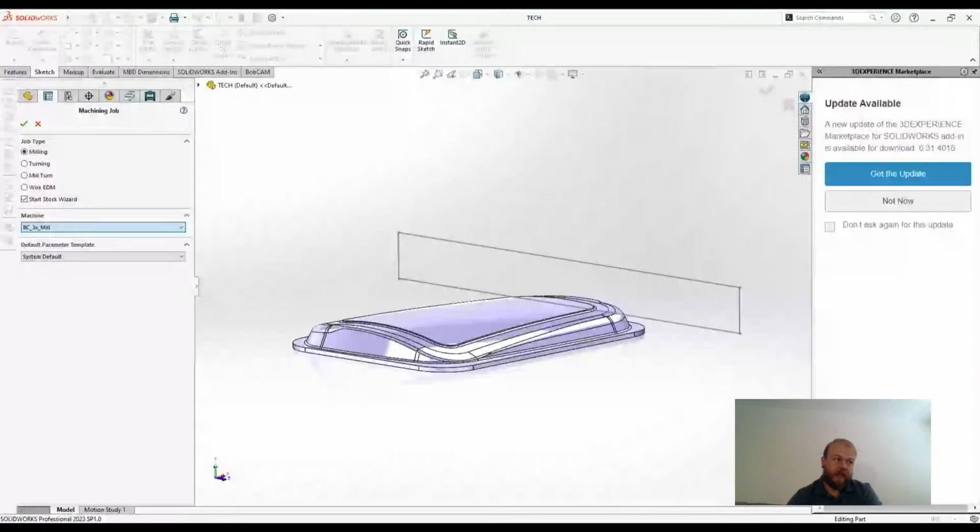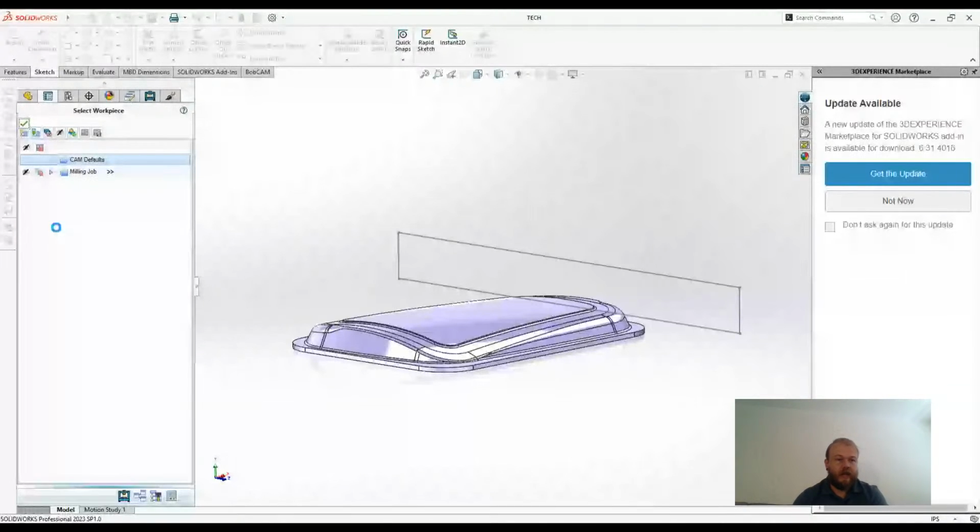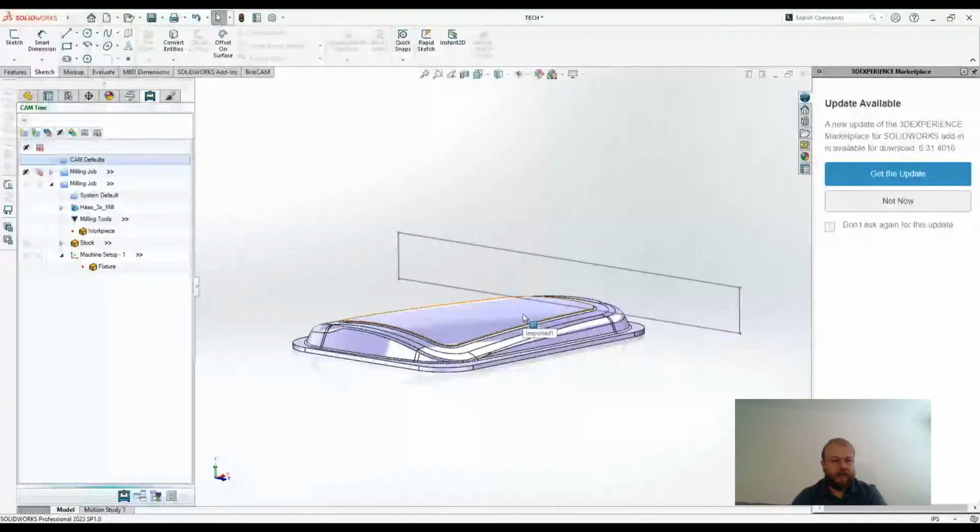we would normally send a post request, so making sure that you have a sample program and the formatting of the G code would be specific to any machine that you're using here. So I'd select a Haas 3-axis machine. I would select OK, select the workpiece, and then select the stock that I'm starting with before going through.